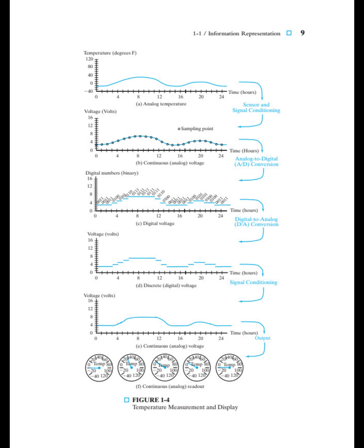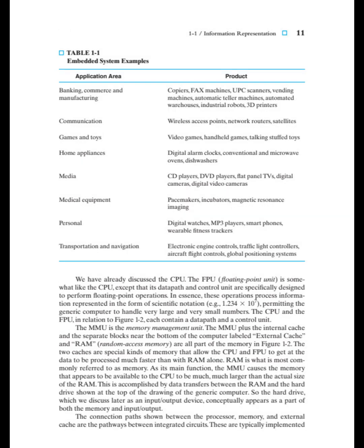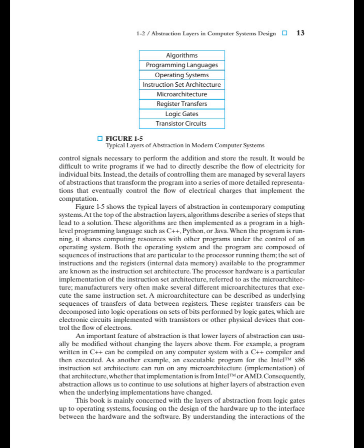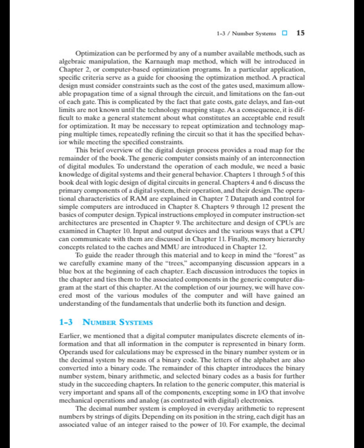And to really show how this digital and analog stuff intertwines, the book gives a great example, a wireless weather station. Oh, yes. Walk us through how that works. Okay, so the outdoor unit has a thermistor. This is a type of resistor, and its resistance changes with temperature. So it's measuring the temperature. It is. That's an analog measurement. Now, a circuit converts this changing resistance into a corresponding analog voltage.